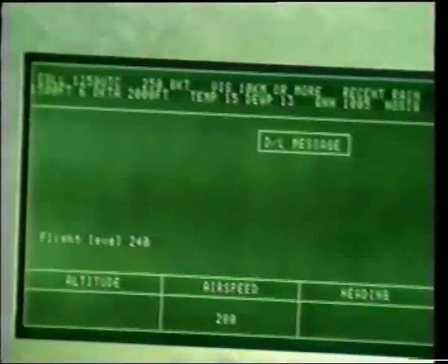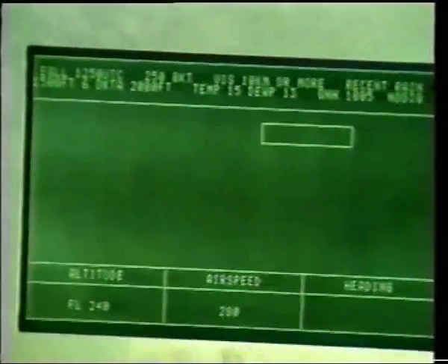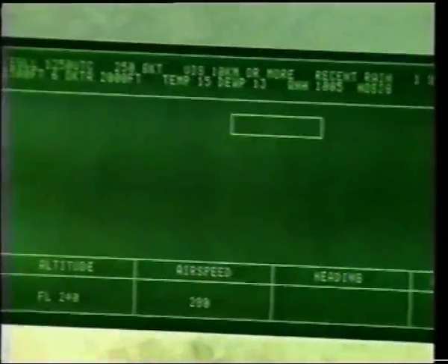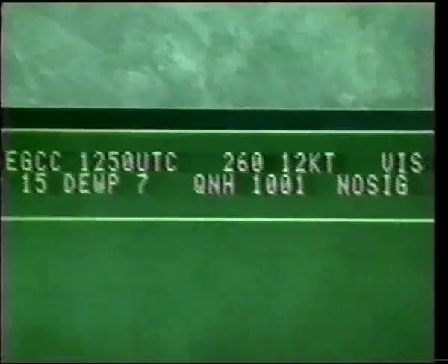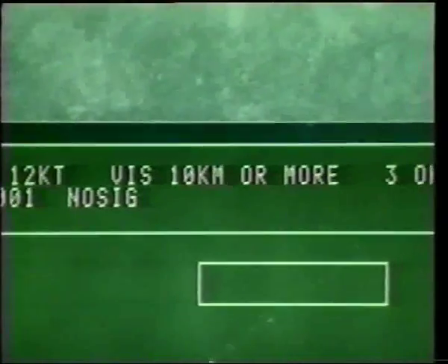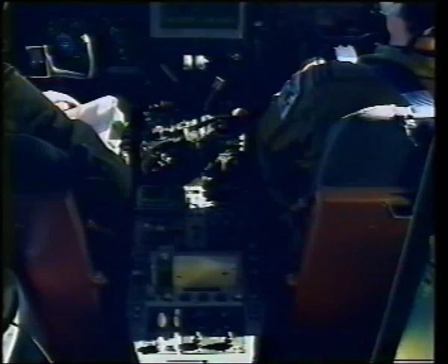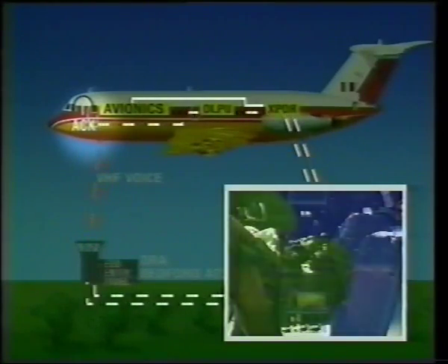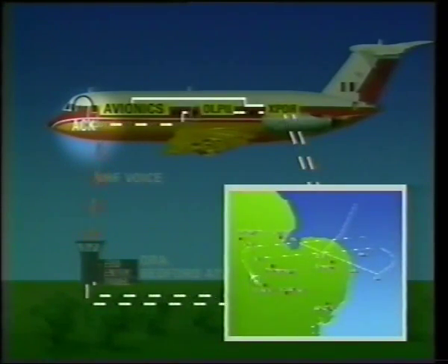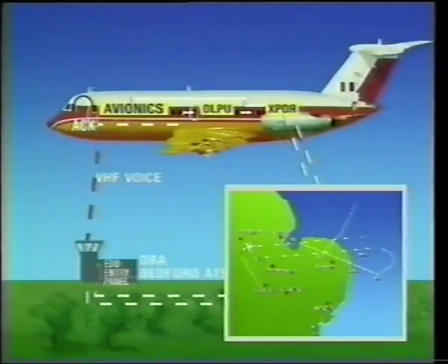As soon as the pilot depresses the acknowledgement button, the instruction transfers to the appropriate clearance box so that all current clearances are displayed. At the top of the LCD display, the latest VOLMET data requested by the pilot is also displayed, replacing the synthesized voice of conventional meteorological information. A small printer situated in the central pedestal offers a hard copy if required. Let's now see these elements at work in the context of the demonstrations.